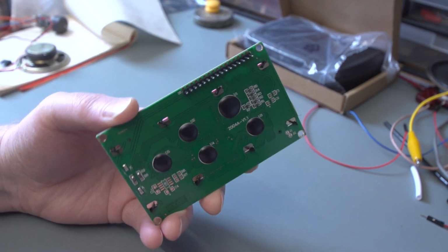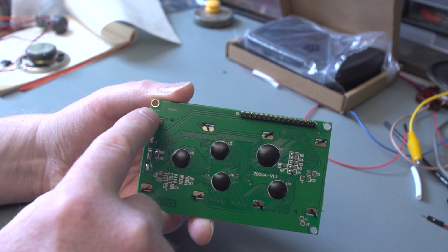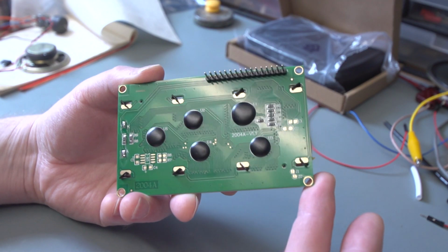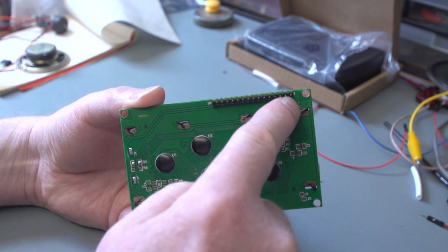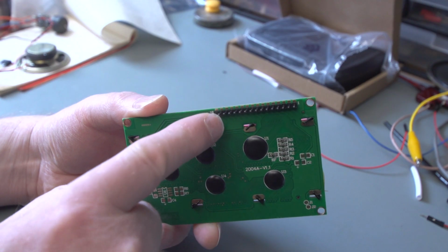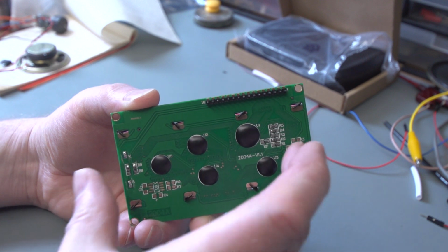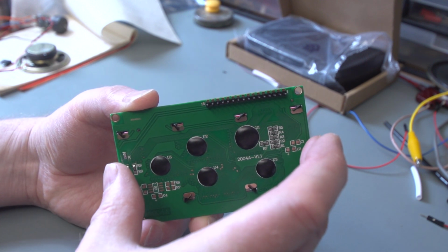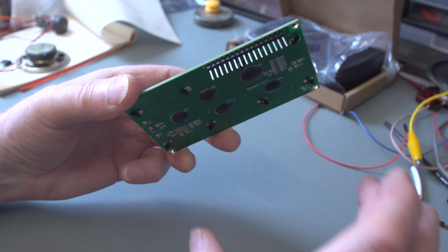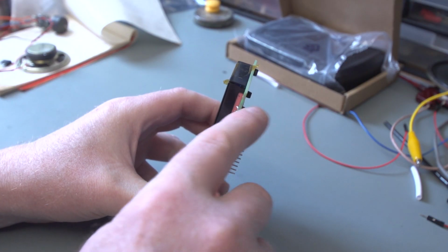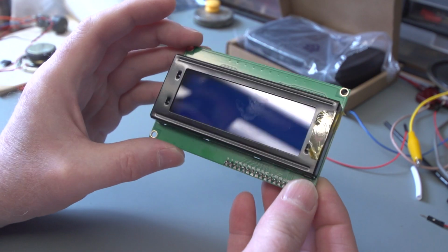Hope that's clear. So one thing we need to do in KiCad is to recreate the footprint the same as the LCD display module, and then we can get the mounting holes exactly correct, and also the position of the header there of the connector. So that will then plug into the back of the LCD unit, and we'll end up with a sort of module with two boards. So the whole thing will just go clunk, and then we can use some nuts and bolts or some standoffs perhaps to get the distance right, and yeah, should be neat.